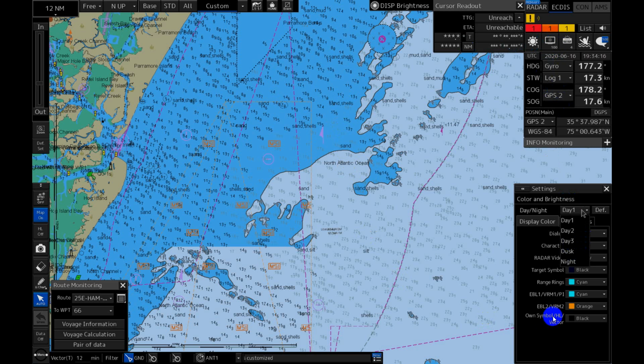One more thing I wanted to add, that for user map, better to use orange color. This is like a middle ground or sweet spot when putting some additional information on the ECDIS chart, because it is not so distracting for the eye, and it will be visible in all modes, whether it is night or day.